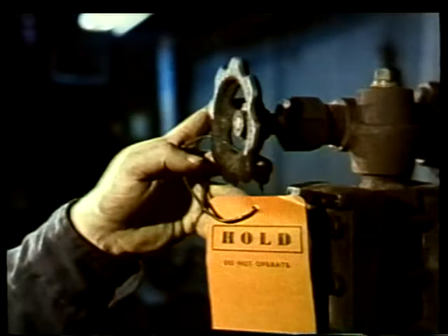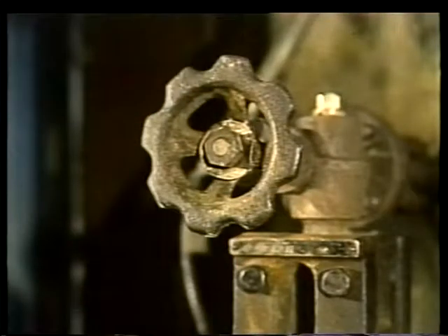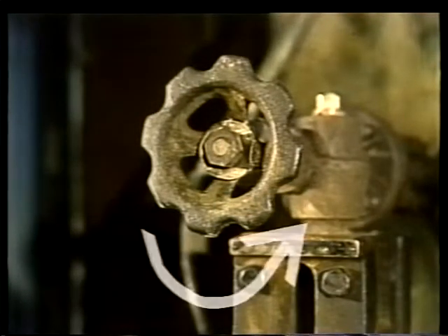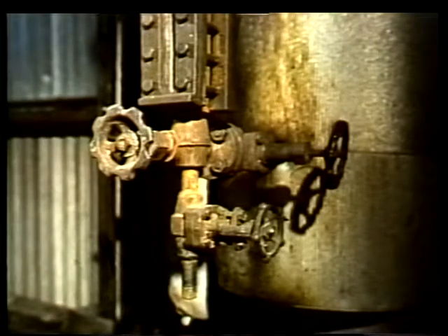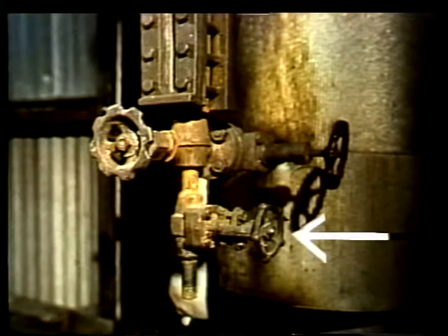If it has been dismounted for maintenance, it must be returned to its regular place. The gauge you will see is not the same one we just worked on, but we will use it to show you how a gauge is returned to service. Clear the tags on the gauge and heat it slowly by opening the top valve and partially opening the gauge drain.